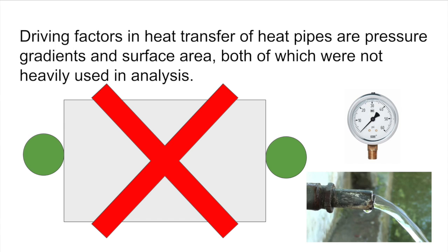In an attempt to control the heat transfer to just the ends, the surface area that provides so much of the heat transfer was restricted. Leaving the insulation off the heat pipe would have provided better results, while making the equations needed much more complicated. While it is possible to do this evaluation, more sophisticated measurements would be needed to compensate for the non-uniform heat transfer patterns. This is evident in the fact that new research on heat pipes is being developed and explored even today. It is a complicated system and requires great care to analyze accurately.